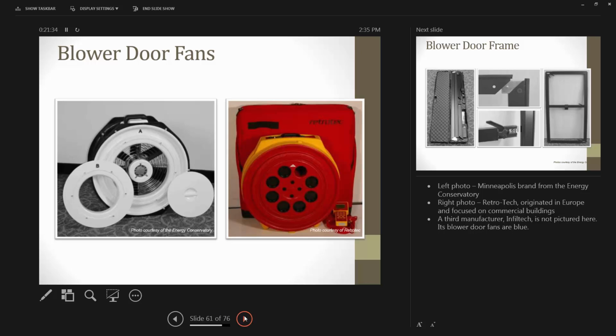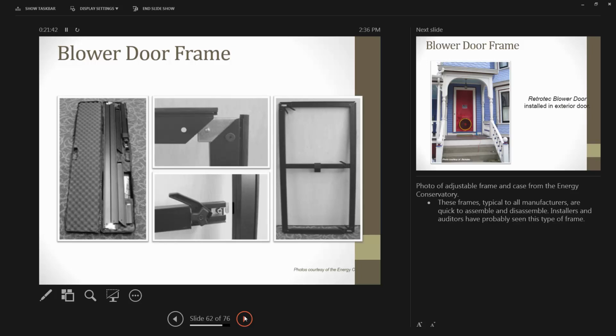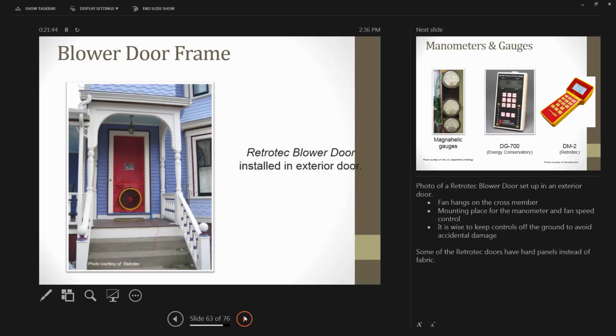And we won't spend too much time on this. We'll actually get to use the real blower doors and see those. And there's an example of one from the outside that's in use, and you can't really see it on this picture. You can if you download it, but you can see that the fabric on the blower door is really pulled back in because it's working to create that pressure inside the house. So exhausting, creating negative pressure inside the house, so it's just sucking that back in.